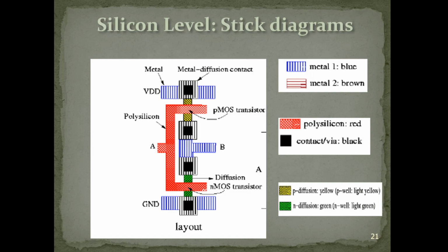What we have here is a PMOS transistor on top, and on the bottom an NMOS transistor, with the gates connected to the input A, and then the metal layer that connects to B would be the output of the system. So to create a MOS inverting gate in this instance, that's how you would do it if you look under a microscope at a chip which implements that functionality.